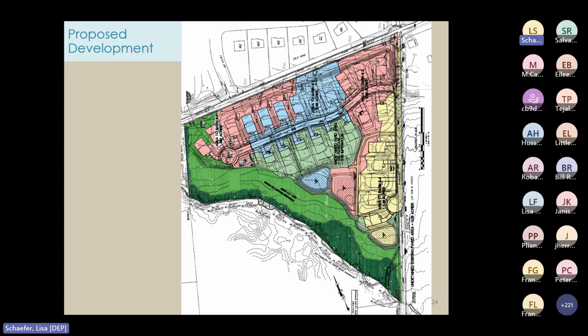All right, we're going to move on and look at each of the basins individually. So basin 1 is on the left side of the image. It's shaded in pink next to the cul-de-sac that's on the west side of the site. Runoff is collected in lawn area inlets and piped to the basin. Plus, the cul-de-sac is graded so that runoff flows to the east more than 50 feet along the curb to the inlet on the piping run, even though the basin is so close to that huge area of pavement.